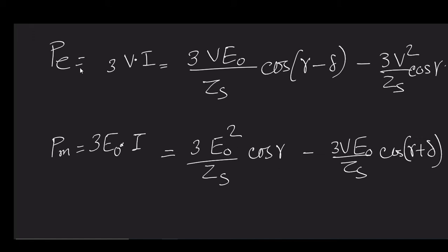Let me repeat what I am saying: even if your regulation value is very high, we are committed to maintaining a certain level of voltage across our machine terminal. So, in case there is a drop in our machine output voltage, we adjust the field current to such an extent that